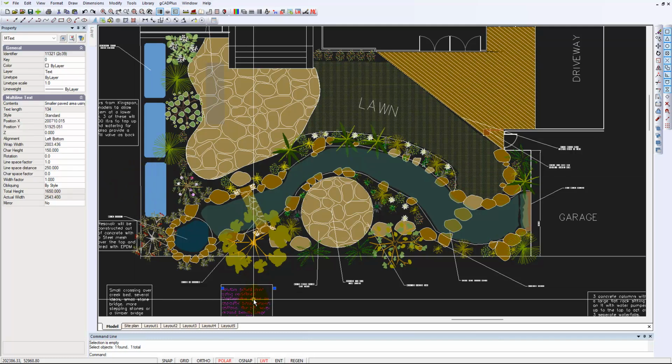I got to this point by looking here. We might want to have that text in there printed with a thinner weight pen. You could do it in the properties box directly here with line weight. It's currently set by layer.